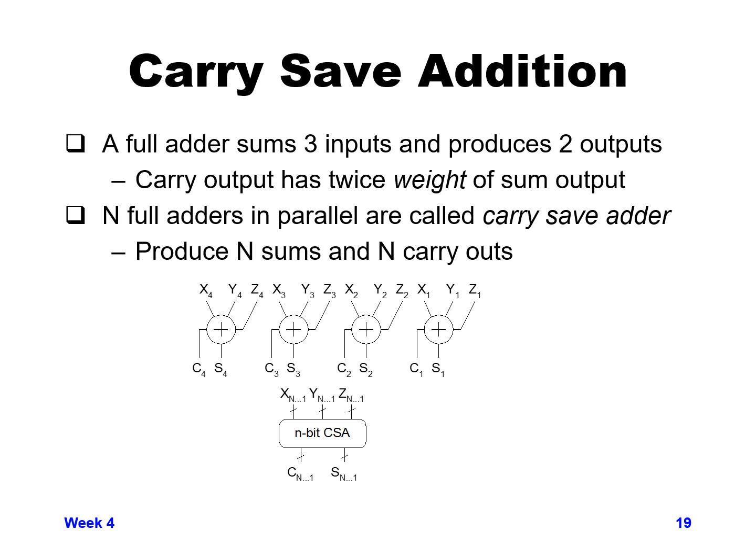So if we look at this in terms of n bits, let's say 4 bits, using these carry and sum values coming out of 4 bits, we have 3 possible inputs. Instead of saying A, B, and carry, we'll say X, Y, and Z. So we have 4 bits worth of X, Y, and Z going in, and we have two outputs coming out, a C and an S. So we get n sums and n carries.